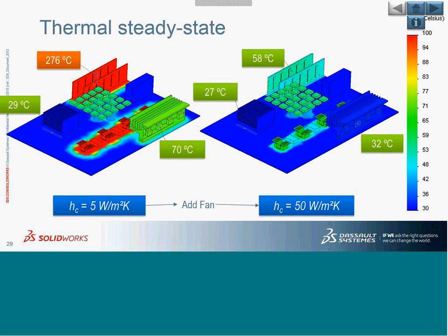When it comes to thermal analysis, convection is treated using the coefficient of thermal convection. We give this value to the software, and if necessary you can also simulate radiation between two surfaces. It could be a basic thermal study wherein you are understanding temperature distributions on a part. You want to understand the effect of using different materials of different conductivity, or the effect of convection on the assembly, or the minimum temperature. All of these can be understood and analyzed using this simple thermal analysis.